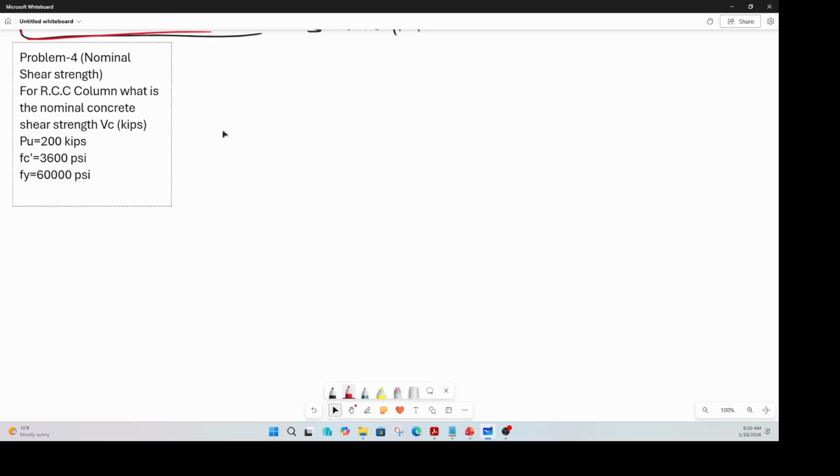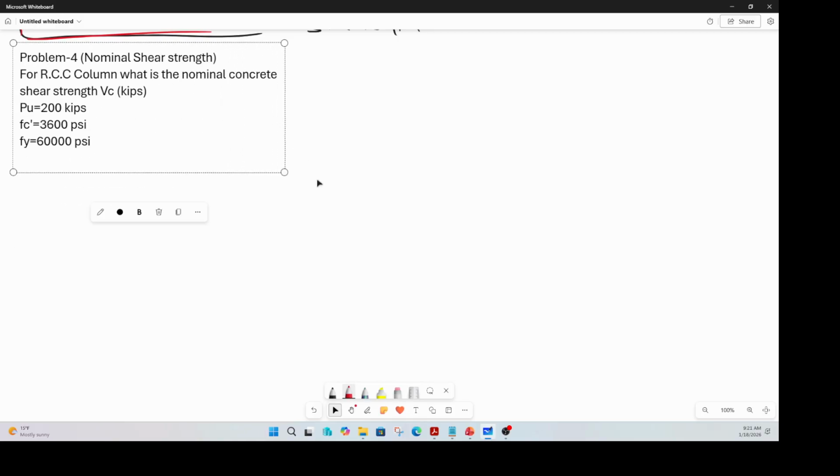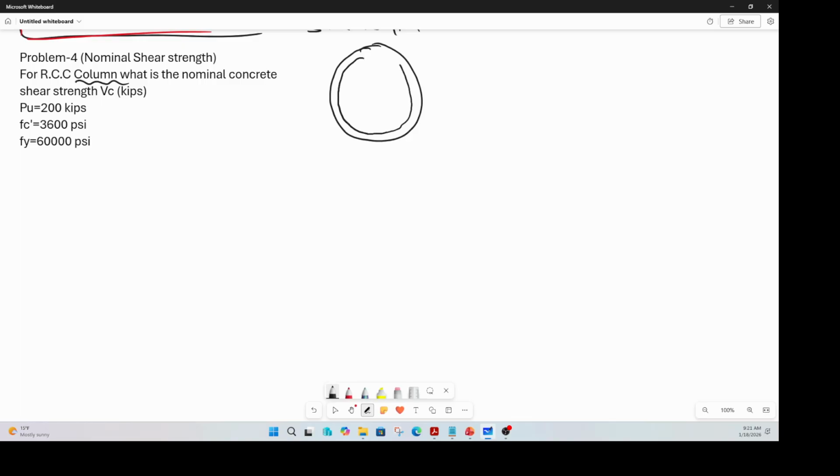flexure. So now let's do another problem on finding the nominal shear strength, but this time is slightly different. Let me draw the beam. It's going to be difficult because it's a circular. So this is a circular column, looks like, right? So this is a column, and obviously there is a spiral, ties, regular ties, right? The diameter of the tie is number 4, number 4 at what spacing? At 4-inch spacing normal to the screen, right?